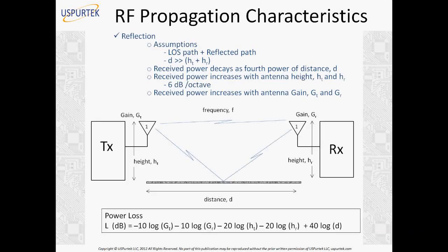Now this is a very practical equation we arrive at to calculate the effects of reflection in this simple scenario. Again, you just enter the gain of the transmitter, the receiver, the height of the transmit antenna, the height of the receive antenna, and the distance. Okay.